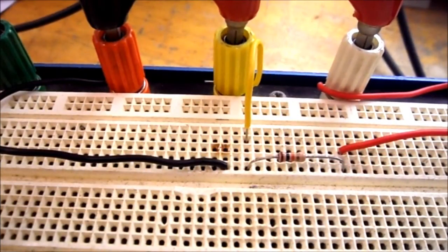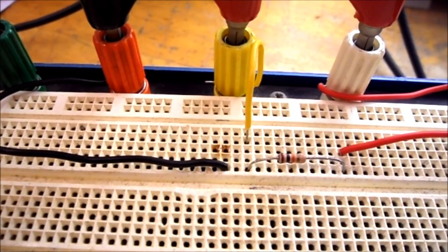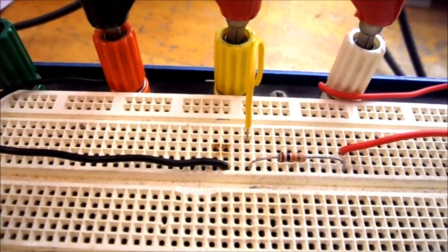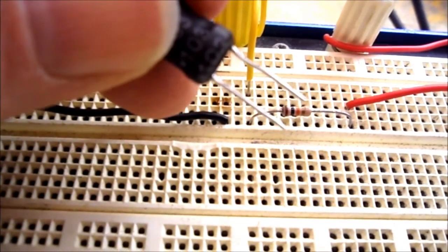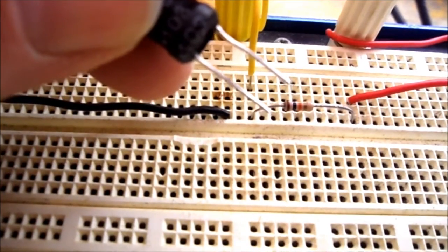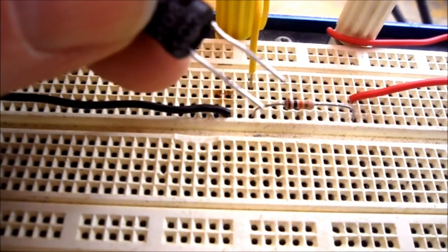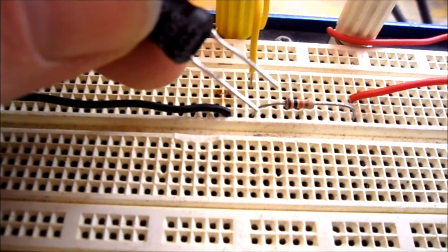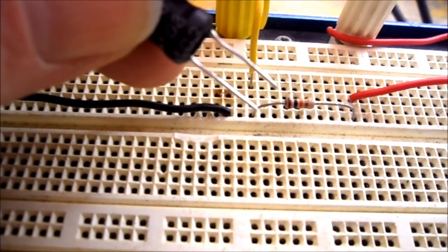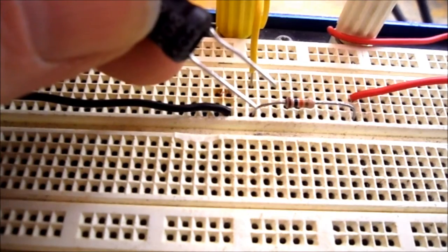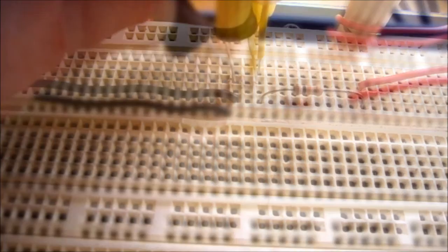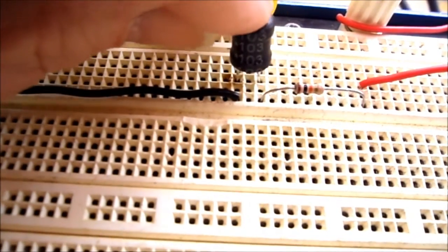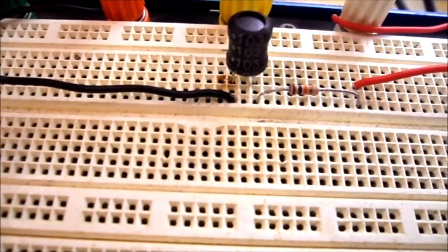I've taken my inductor out so you can see that the yellow wire does indeed connect with one side of the resistor. It's very important when you're putting the inductor in the circuit that you don't spread the leads too far apart, or they will break off the inductor. The inductor itself is made of very, very fine wire, and these long legs are soldered to that fine wire, and if you pull on them too hard, they'll break off the wire. So 103 is my 10 millihenry inductor.